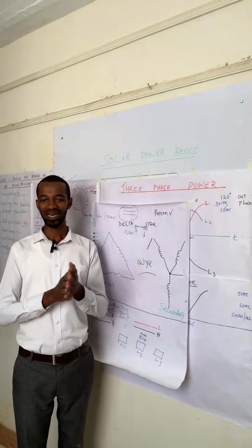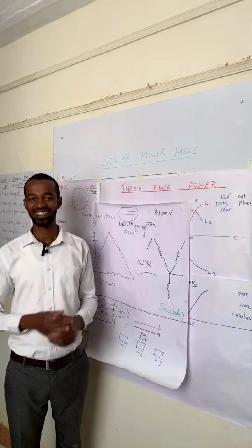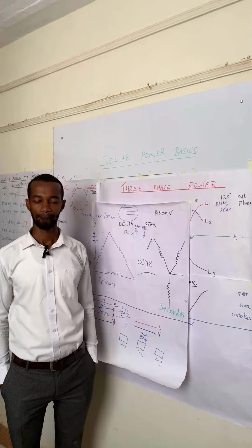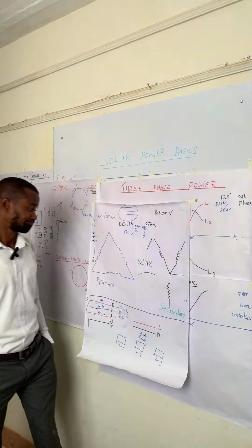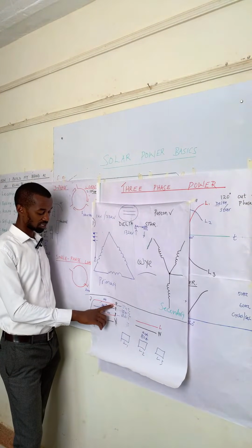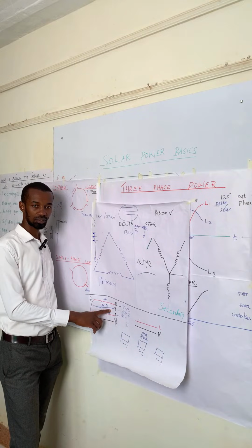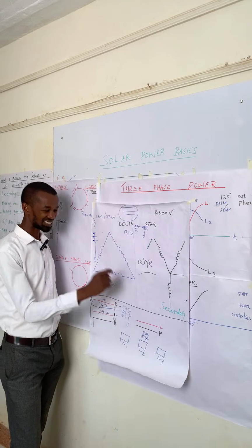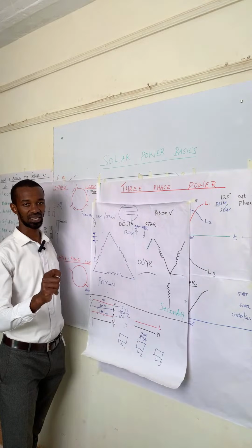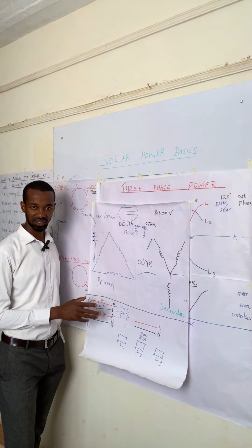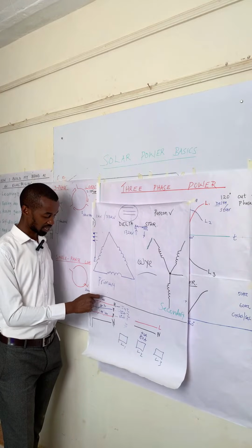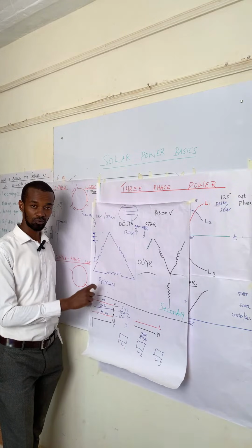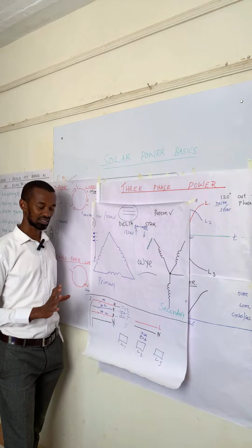And Maggie, you have something else? Yes. Pattern is asking, if there is a surge, can it be stopped by a fridge guard? No. If that surge travels through the secondary conductors from the transformer, and in your house you don't have a surge diverter, not a fridge guard, not an AVS 30, those are just switches that monitor the voltages, and especially at the point where the power is off. They will allow voltage to flow in case the voltage is within a certain limit.